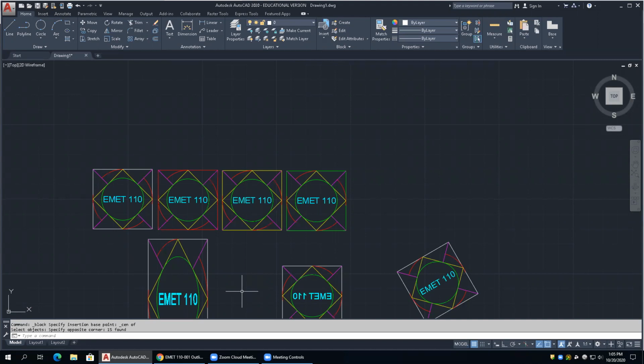All right. Did anybody's blocks move? Well, they probably moved. So why do you think they moved, Shelley? Because you didn't pick a new base point. So what happened was, or you did, if you did pick a new base point, it wasn't the original base point. Did you find your blocks? Type in Z, enter, E, enter. Yeah, okay. So you didn't type in any base point, so it used 0,0. It displaced everything. I clicked for a base point. Well, maybe you didn't click on it. Okay. All right. So that's usually your common problem.